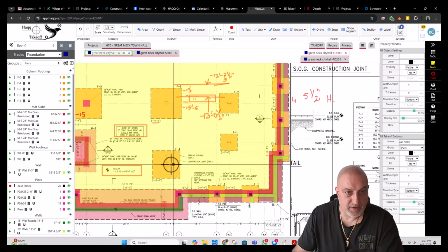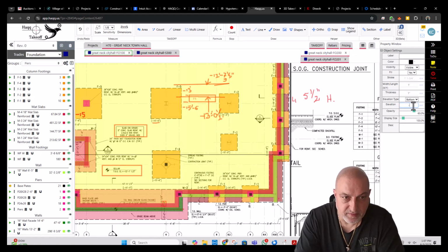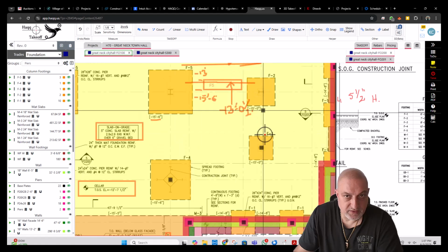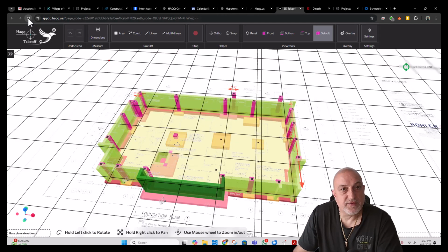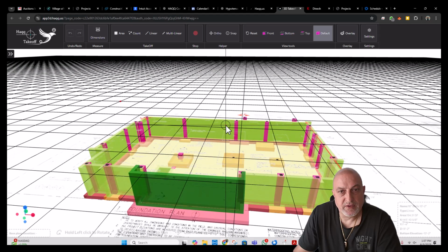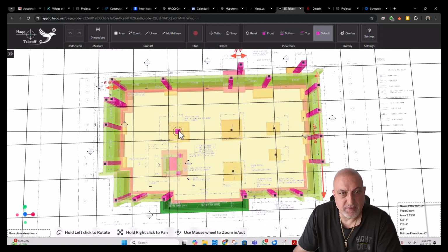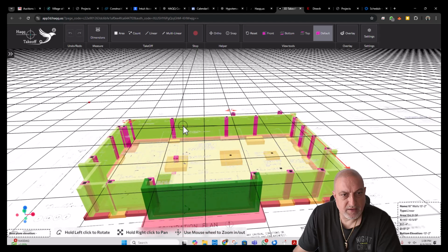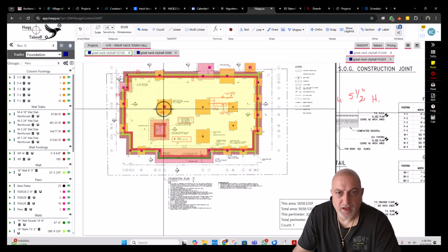Okay, now interior ones, what I'm gonna do is change the elevation on 1 to bottom elevation minus 12 foot 7.5 inch. And I'm gonna copy this one so I don't have to change the elevation on the others. It copies together with the elevation in it. So let's refresh here. It was actually showing already. See, you can see the base plates, the black squares, and here. Did I miss on this one? Something wrong with this pier. Okay, now it's there. Just not showing.